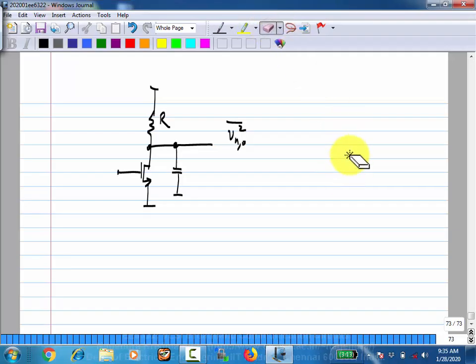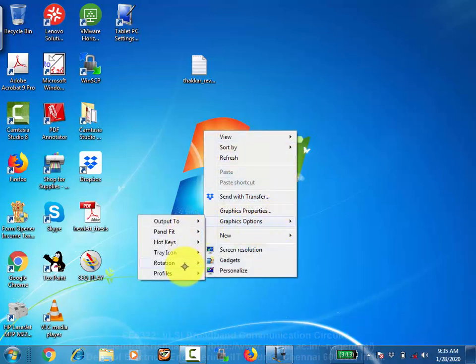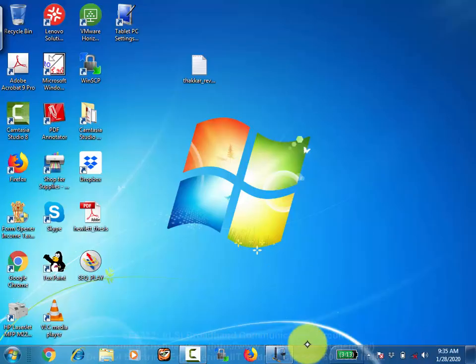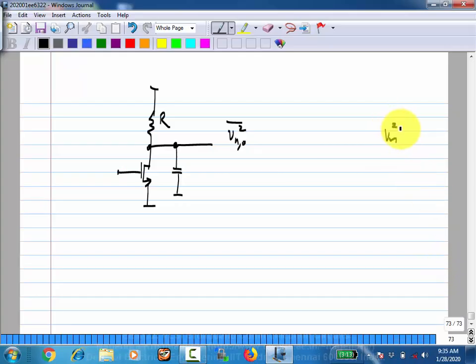So I want a circuit that will give me half of this noise variance. And let's say I don't want to do anything too intelligent, because I can't rely on suddenly being able to invent a new circuit, but I want to just modify the circuit to get half the noise. What can I do? I can double the capacitor alone. I don't want to change the function of the circuit, right? What should I do? R and C both, that's it? And the MOSFET. There are three components.